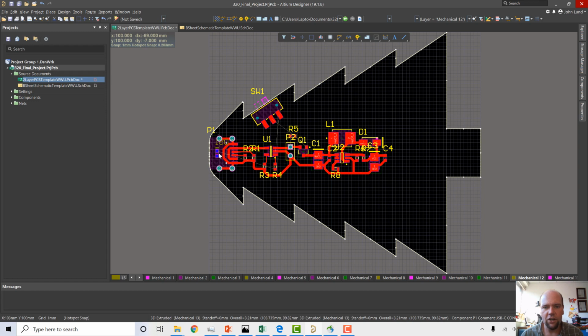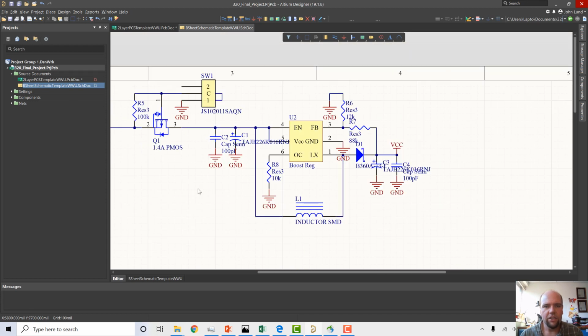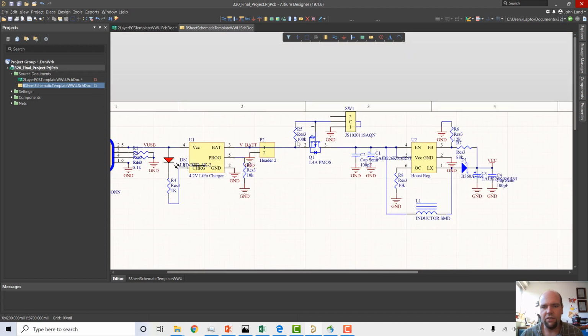Let's do another change. One thing that's pretty common is, if we go back to our schematic, this is great if our entire circuit works. If everything in our circuit works fine, everything's going to go smoothly. But a lot of times, especially if you're doing a prototype circuit, you realize fairly quickly that something's not working right. Or you're setting it up and all of a sudden you get a ton of current and something's broken. So normally, if you're doing a prototype board, you're going to want to put a bunch of test points and a bunch of 0 ohm resistors.